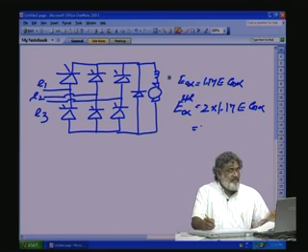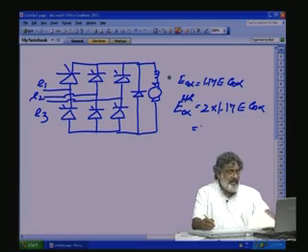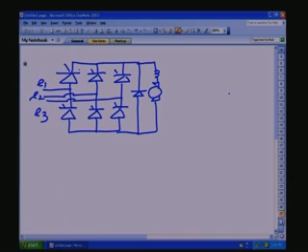So, this we can easily derive, or we can draw the ripple and find the integration also, we can find out that one. Okay. Now, if we put an output diode, whenever the output voltage ripple goes negative, the load will freewheel through the diode. So, that means the negative portions will be clamped to 0 level across the load. So, this means with the firing angle we can have 0 to positive voltage here.